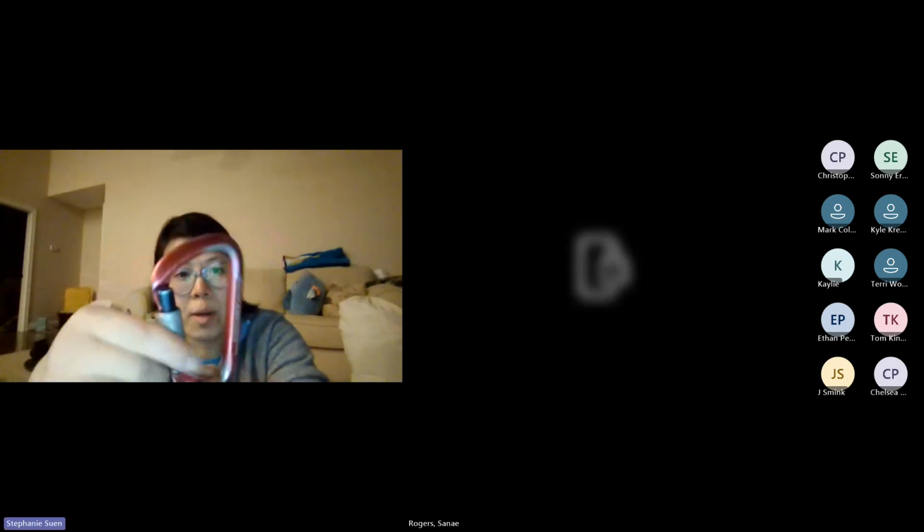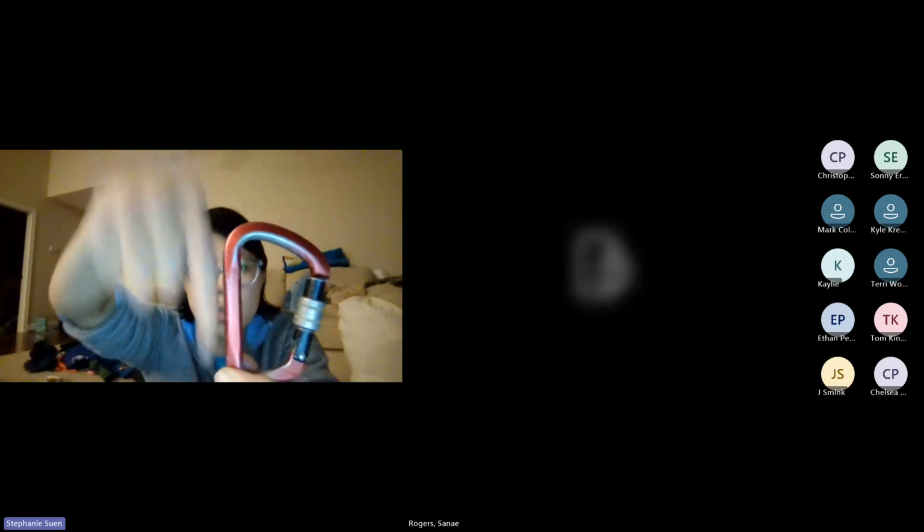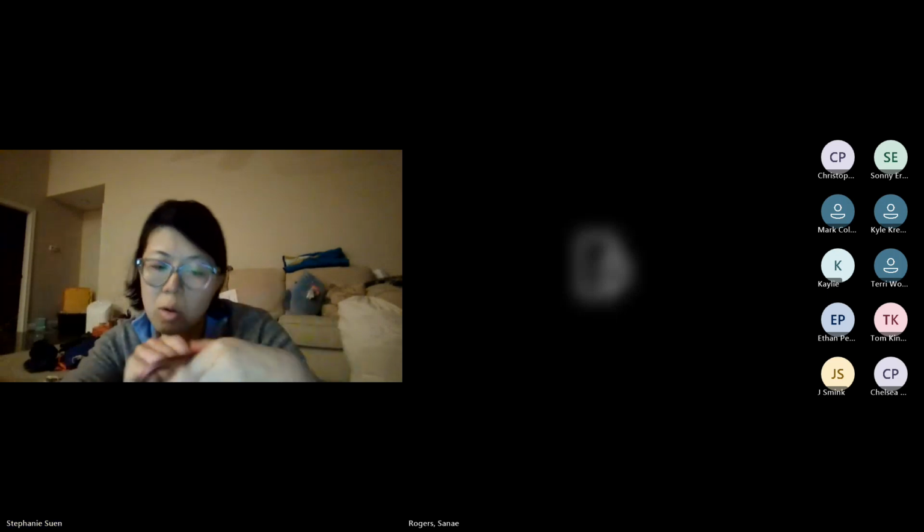Inherently, with an opening there, this is going to be a weak point versus this solid piece of metal here. So we'll talk a little bit about carabiner strength. For most carabiners, you can read the rating along the spine off the carabiner itself. This one says 22 kilonewtons, I believe, as well. Trying to read it upside down, 27 kilonewtons along this spine, right? So that's my strongest portion.